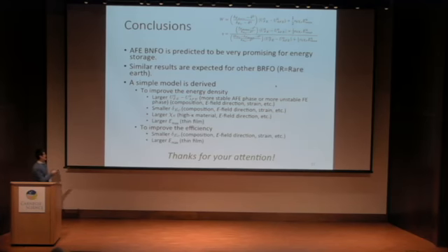It's better to have small delta EC, and large dielectric constant by using high kappa materials or changing the conditions. It's also good to have large Emax. Usually thin films can sustain a higher field. And to improve efficiency, it's important to have small delta EC and large Emax.